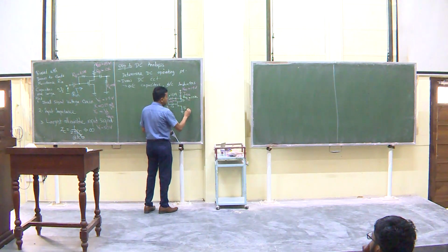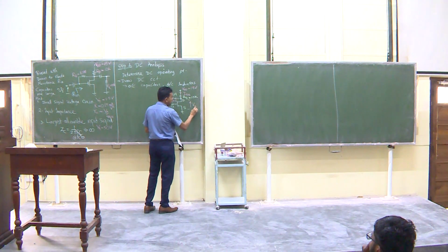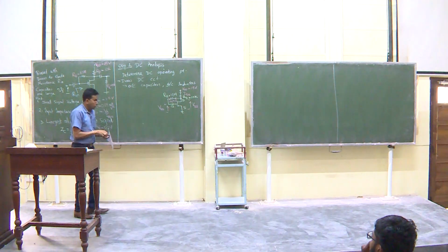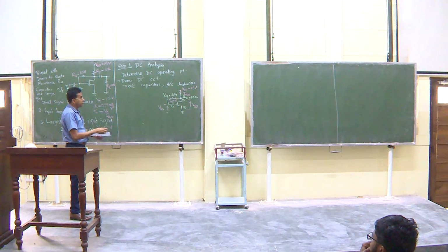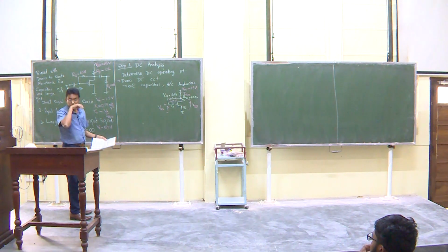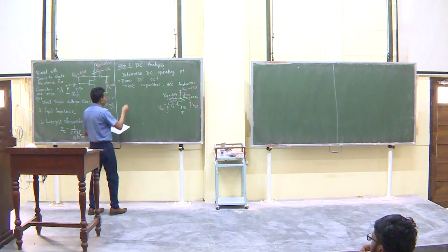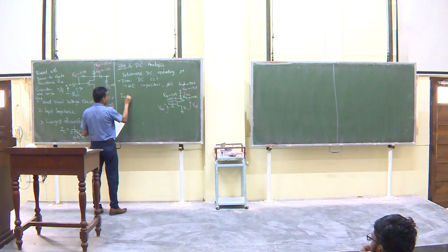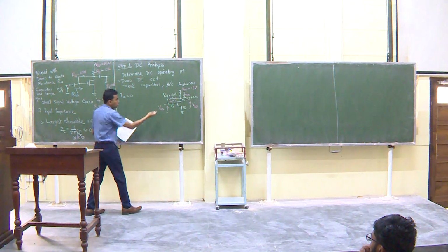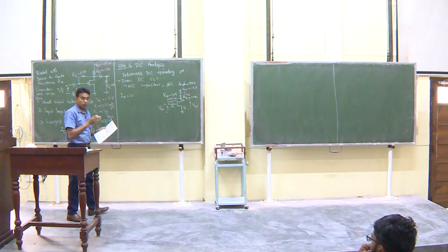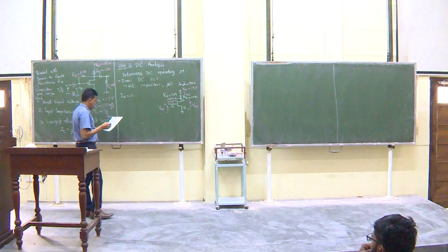The voltage here is VDS. So, it is a matter of finding IDS, VDS and VGS, so that we can compare those values, right. We know that IG is equal to 0 because it goes into an oxide layer, so large input impedance.